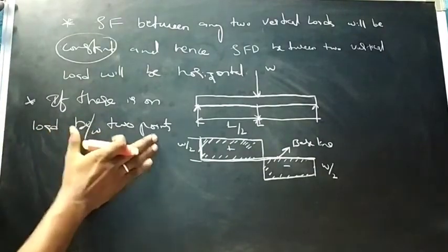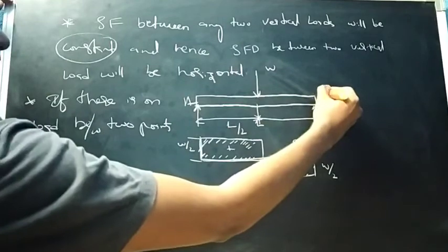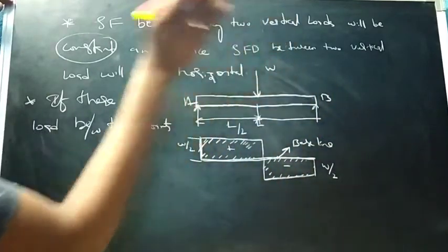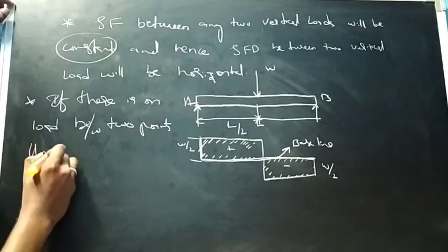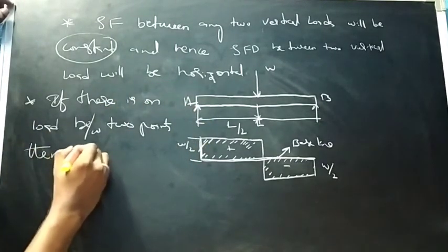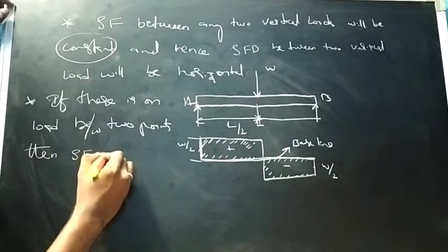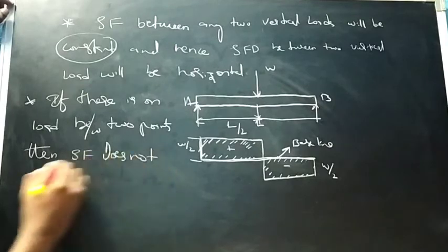If there is no load between 2 points, let's say this is A and B, let's imagine there is no load between 2 points, then the shear force will not change. Then shear force does not change.